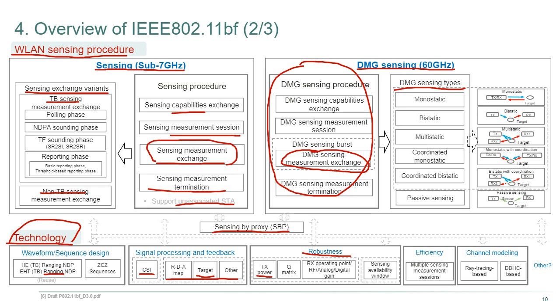And also the Q matrix should be identical: not swapping the channel, not swapping the antenna, and not adding beamforming to this measurement, in order to not add unintentional changes to the CSI measurement result. That's very important. And also, we can further feed back the AGC or operating point information.